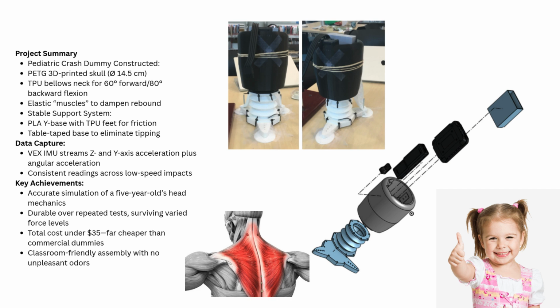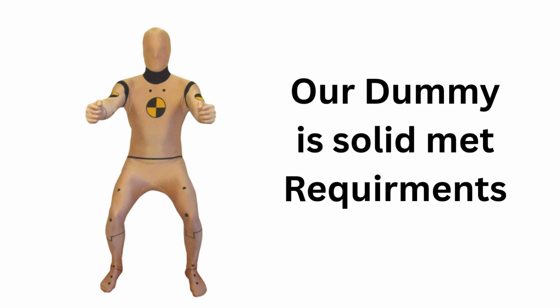Ultimately, by using this design, we were able to effectively model a 5-year-old girl's head during a low collision impact and was able to harvest Z and Y acceleration as well as angular acceleration data using VEX hardware. It was a cheap and effective solution with a minimal amount of steps compared to other industry dummies. It was also generally aesthetically pleasing and did not have any strange odors.